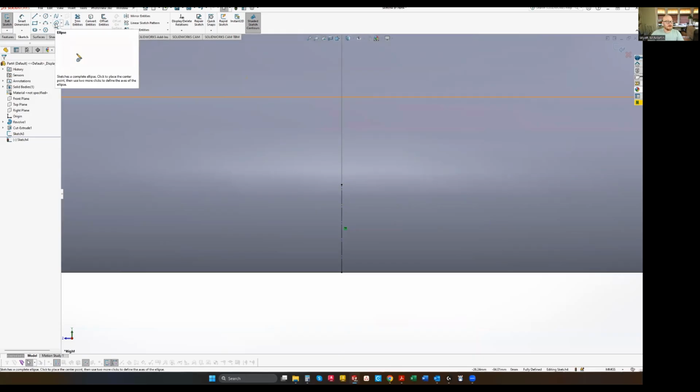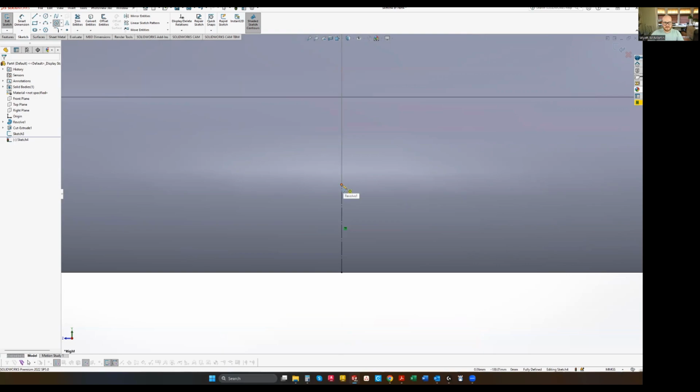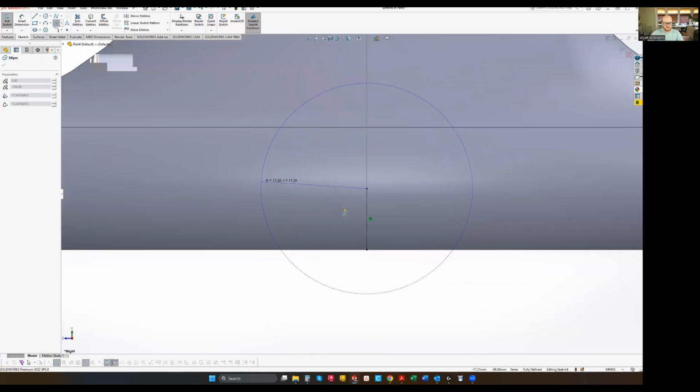We can zoom in a little bit and make it so you can tell that it's for construction. And then let's grab our ellipse tool right there. And starting on the top of this line, we're going to drag straight out to the left. Make sure it's straight out. There we go. If it doesn't work, you can hover over this line, and then when you come straight out, it will be perpendicular, just like that, and then come straight up.